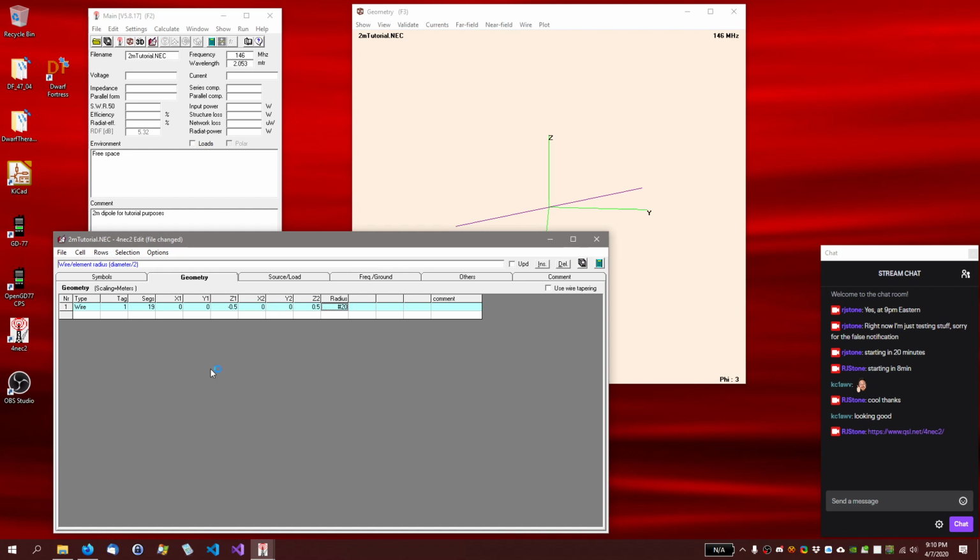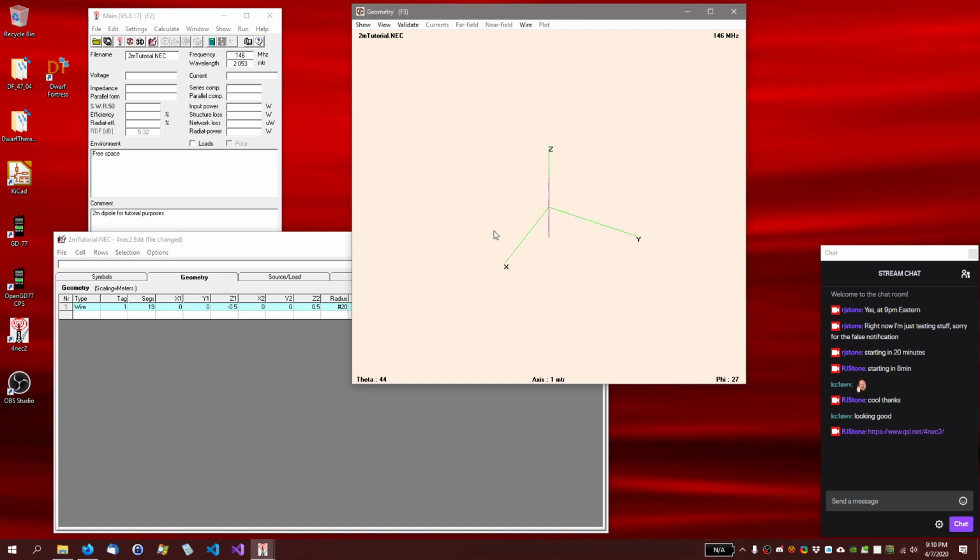And then our radius is 20 gauge, whatever the radius of a 20 gauge wire is. So now when we click on this again, we're actually going to get a wire going vertically. There are some things up here we can do. Show segments will show a little circle in every segment to give you an idea how many. Actually, I guess it's not in the middle. I guess that's the dividing line of each segment.